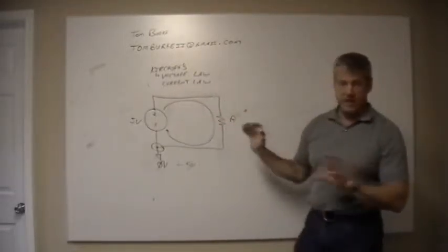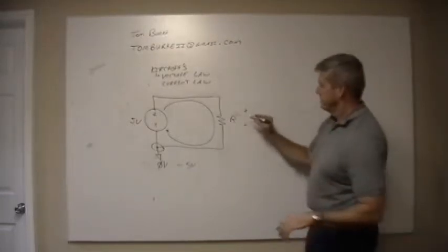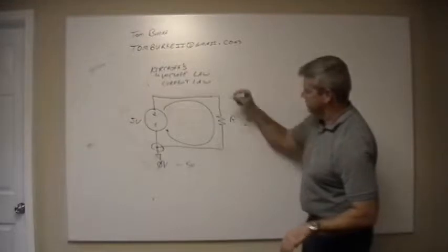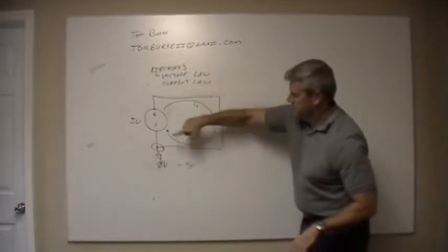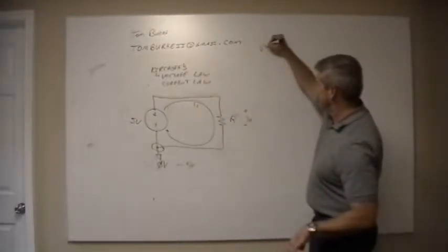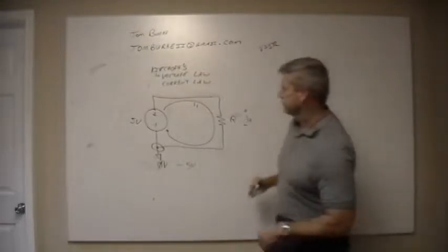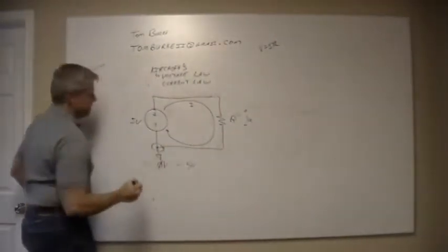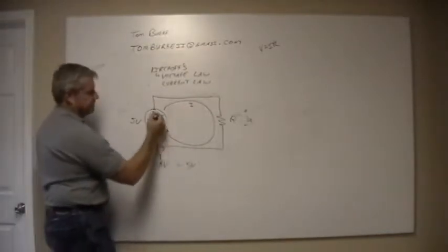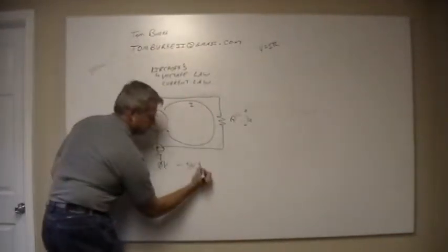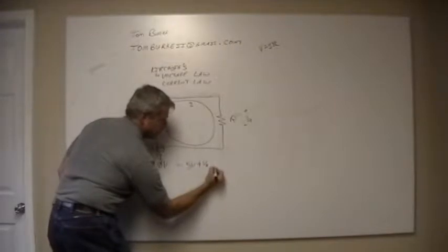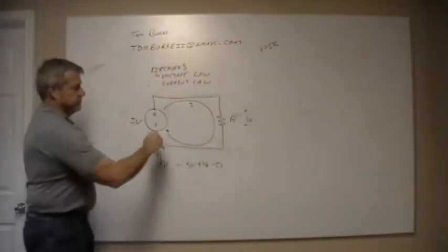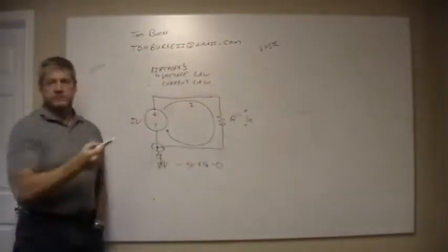But you don't have to say it will be, you can just choose. So we'll say plus VR, because there's going to be some current flowing in the circuit. Remember, V equals IR. That looks like an H, I'm sorry, I. So minus 5 volts plus VR equals 0. So the sums of those voltages must equal 0.